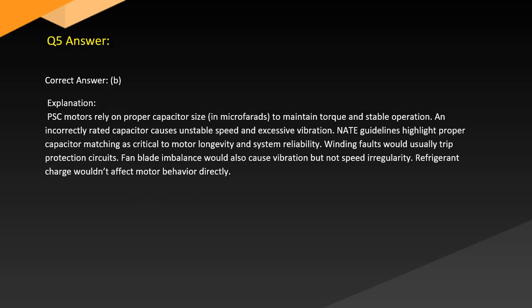Answer. Correct answer: B. Explanation: PSC motors rely on proper capacitor size in microfarads to maintain torque and stable operation. An incorrectly rated capacitor causes unstable speed and excessive vibration. NATE guidelines highlight proper capacitor matching as critical to motor longevity and system reliability.